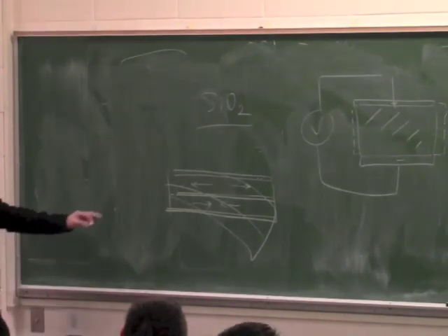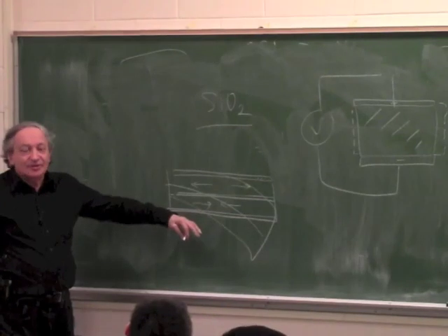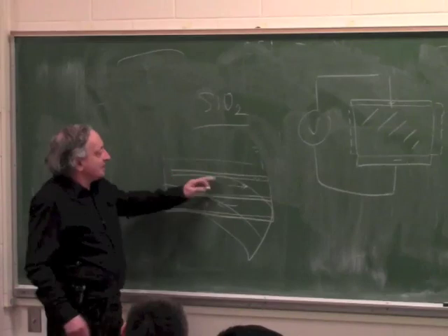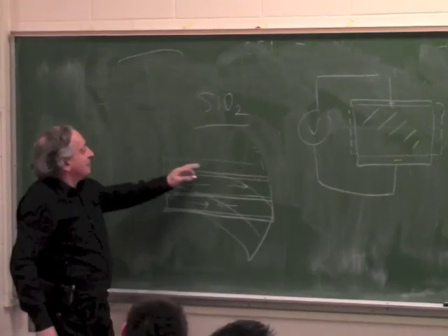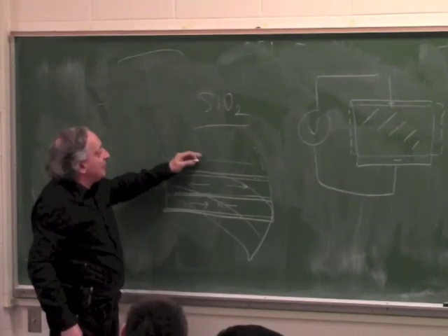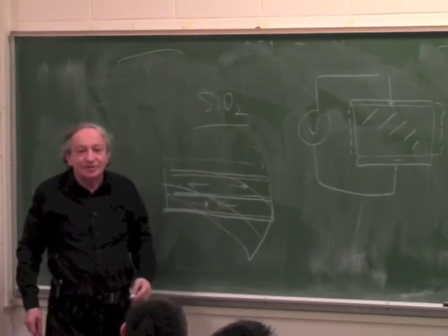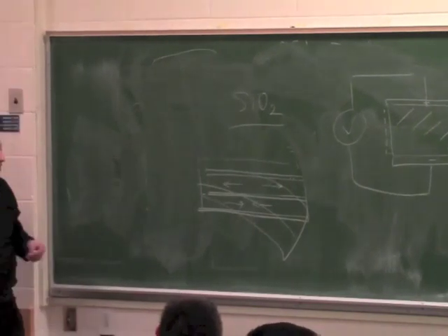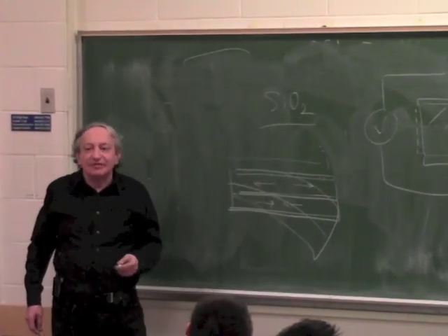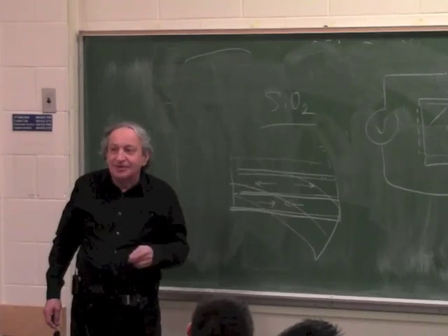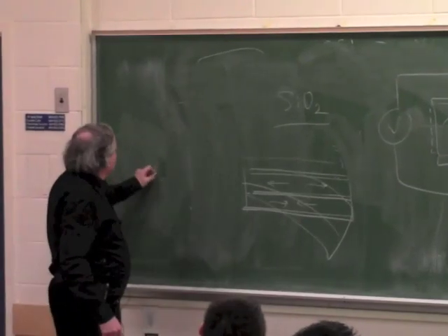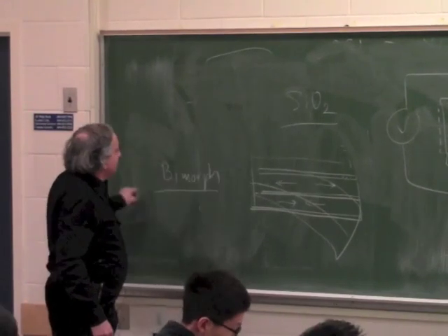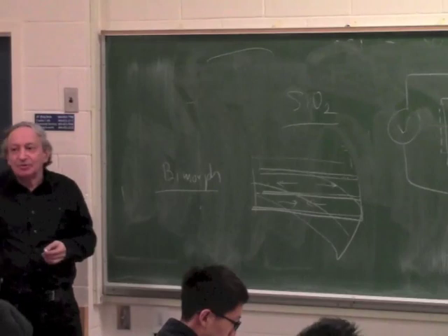Now here you're amplifying the effect a lot, because if this is a centimeter beam, and even the top is not just a millimeter but a few microns longer, the beam will bend a lot, right? Because it's a huge magnifier. If the beam has 0 thickness, the magnifier is infinity. So this is called a bimorph, and that is used a lot when you want to amplify the piezo motion.